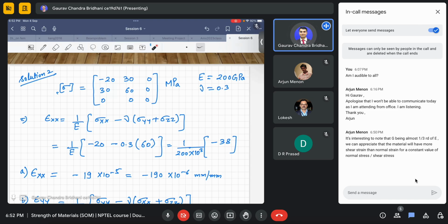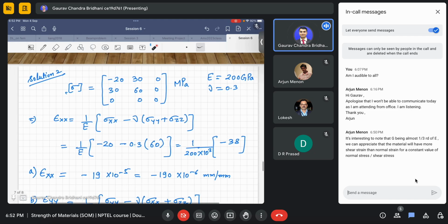So as we have gone through the Mohr circle for stresses, there is a similar Mohr circle for strains also. If you see for the case of pure shear, the Mohr circle will be about center basically for strain also. So when it is about center, the radius of the Mohr circle will remain the same. That means whatever is the value of shear strain is the same value of maximum normal strain also. That is one of the examples.